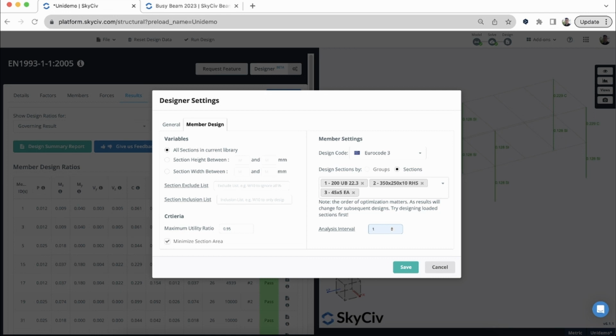So it's going to take a little bit longer because we have to re-perform the FEA. Otherwise, if we increase it to say 5, we can have a happy medium where we're only rerunning the FEA every 5 sections. And the sections are ordered by area, so they are somewhat relatable. So you can do something like this where you're only running the FEA every 5 sections and still get some pretty good results because the deflections are still updating by the area.